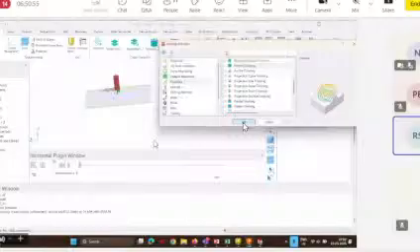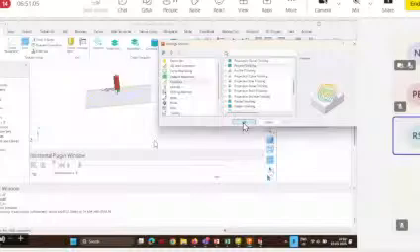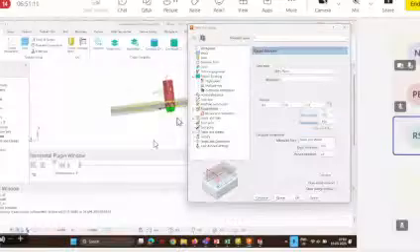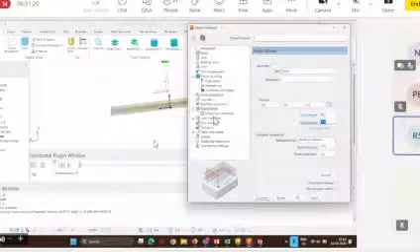Here you can select this curve 2, and then the remaining height we can specify. Since you can see over here, the tool is going inside this material part because the rapid height is quite low. We can put it a little bit higher. And the rest we can just click calculate.